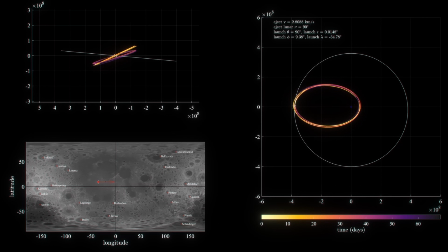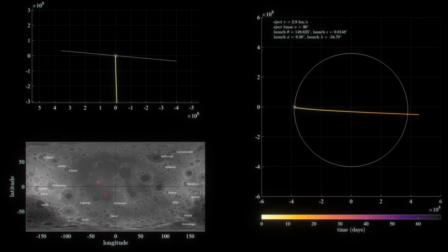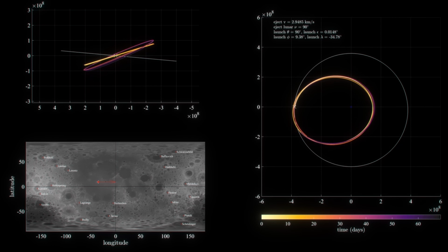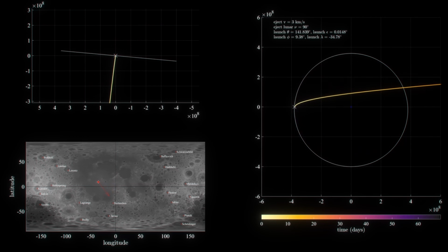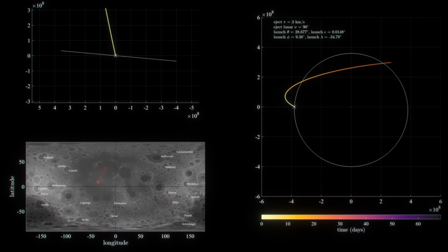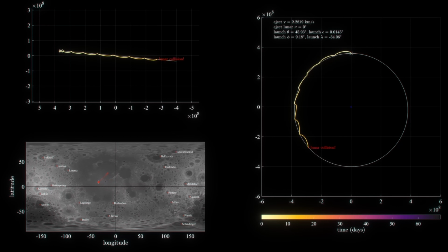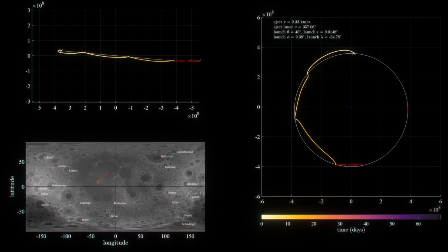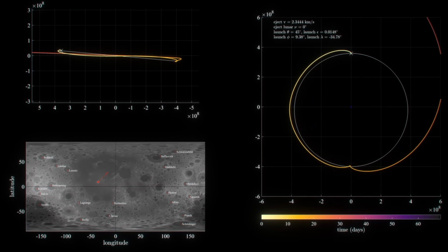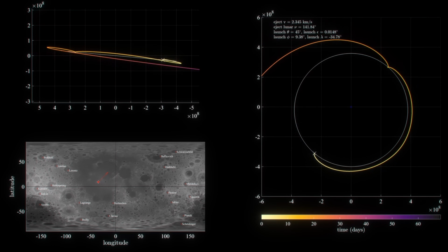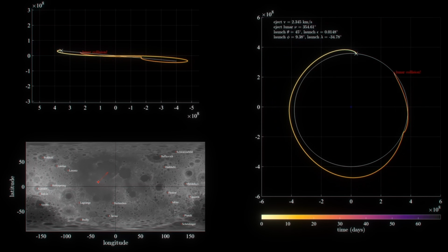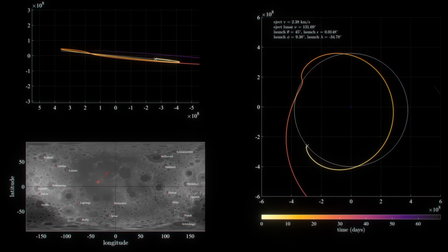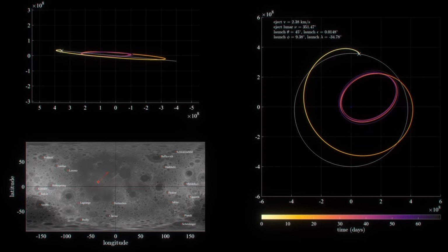The opposite trade-off exists near 0 or 180 degrees, where the mass driver is aimed toward the lunar poles. Those trajectories are better for setting up inclination changes, both through the rocket pod's own burns and through lunar gravity assists, but they are not as useful for the in-plane energy change we need to drop down toward low Earth orbit. So rather than choosing one extreme, we split the difference. We set the launcher azimuth to 45 degrees, then let the optimizer control ejection velocity to control how retrograde or highly inclined each departure becomes. This gives us a little more flexible family of exits instead of locking the whole system into one narrow trajectory type.